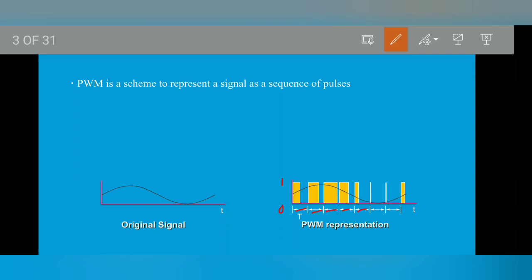For this one, we know the PWM frequency, and if we integrate this part, we can get this kind of average value, and further if we integrate this part, we get this kind of average value. If we combine all the points, we get this kind of structure, the original signal. The higher the PWM frequency, the closer we get to the original signal.